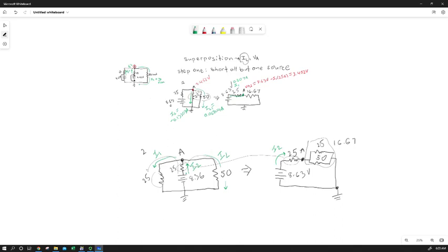So let's start with our I2. So we have a positive I2, which is going to be equal to the whole current flowing through this loop. Well, these are the same numbers as we had up here, except we're representing a different source as the source. It's this one, not that one over there. So I2 here is the same as I1 up there in magnitude. So we have 0.207 amps going towards A. So if that's positive, it was negative over here and it was a different number. I load is going to be equal to VA divided by 50, and I1 is going to be negative. It's flowing away from node A, so there's our sign convention, VA divided by 25.